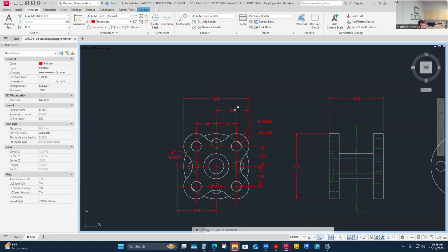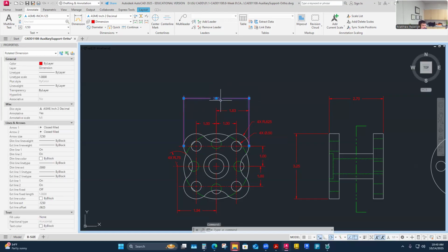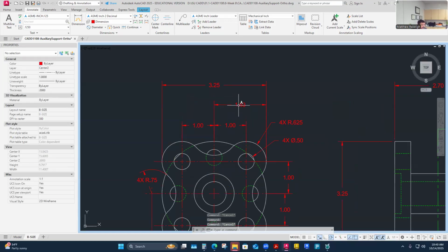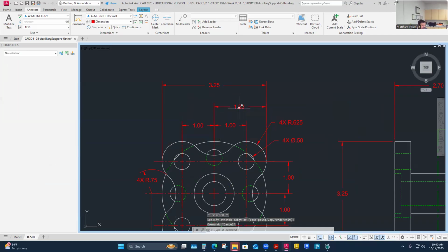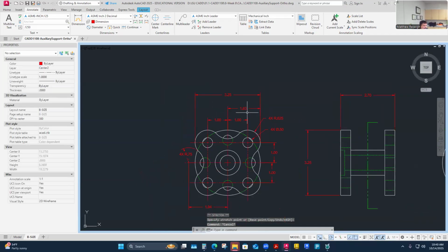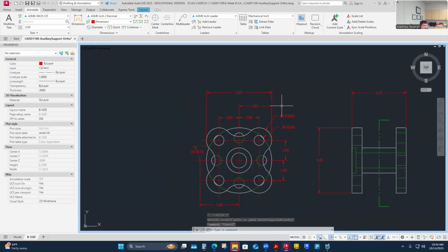This and this are now, I feel like they're kind of talking together where I'm saying, oh, this is 0.163 over. And then I come back from that to this overall diameter. And maybe this still just becomes a reference dimension, but I feel like this is maybe the bigger control here for the overall size is adding that one dimension. So I'm 0.163 and 0.194 out. That's clearly that.